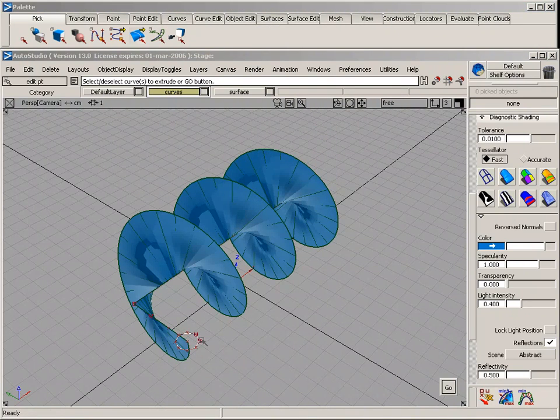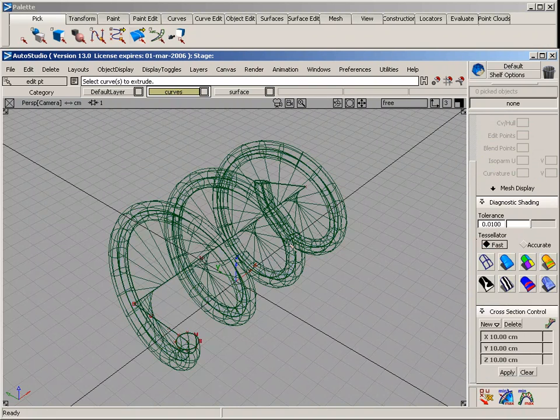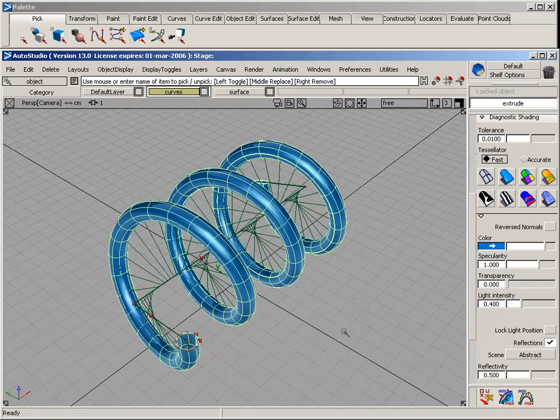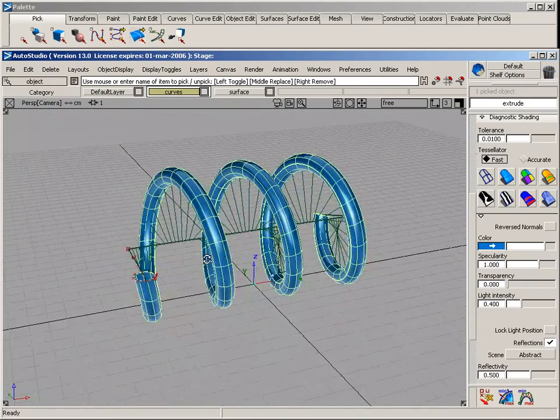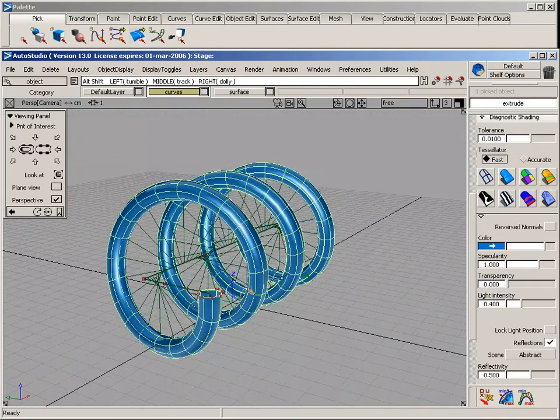Again, notice that the curve turns white and it's asking me to activate it. Next, click on the edge to create a rail surface. Sorry, an extruded surface. I could also use the rail surface tool for this. This now, with this profile being circular, looks or starts to look like a spring. If the profile was more of a rectangular shape, then this could become, for example, a bottle thread or similar.